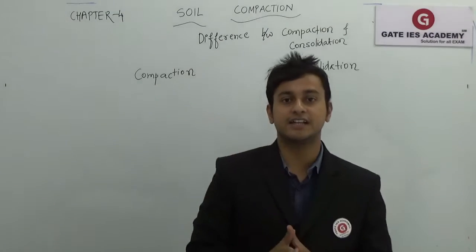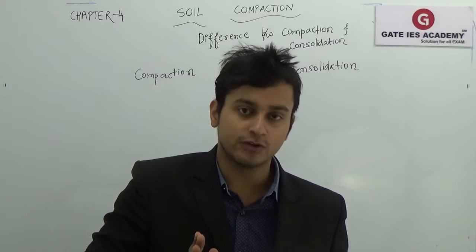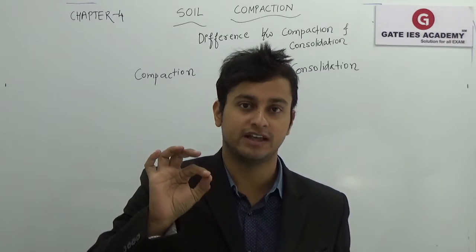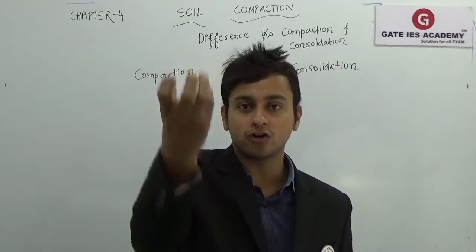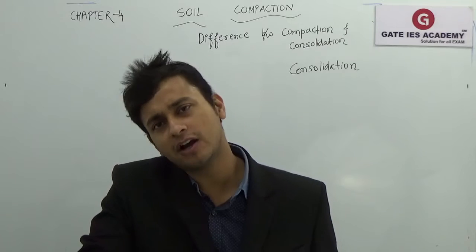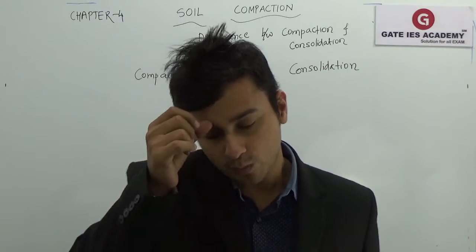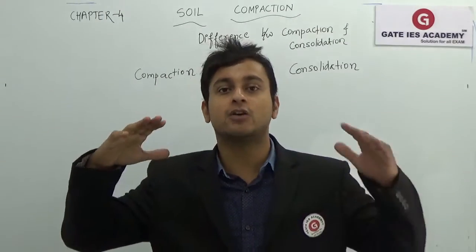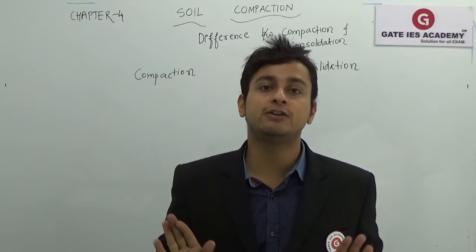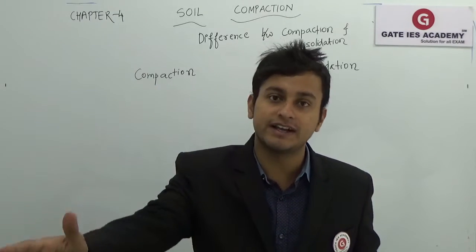Okay, so now let's study the difference between compaction and consolidation. Firstly, I'll try to tell you that compaction is obviously an instantaneous phenomenon. As you apply the loading, automatically the air voids will be decreased. But consolidation is a time-dependent phenomenon. In consolidation, generally, when you apply loading, these are constant loadings which are kept. We keep the loading and allow the soil to settle. How does it settle? Firstly, it is a saturated soil.